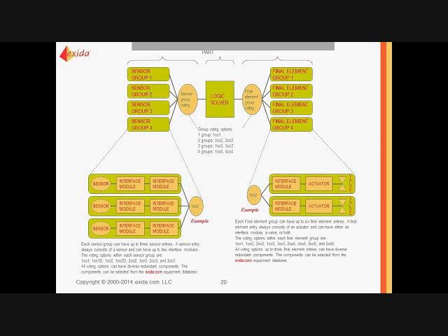A sensor entry consists of a sensor with 2 interface modules and voting options of 1 out of 1, 1 out of 1D, 1 out of 2, 1 out of 2D, 2 out of 2, 1 out of 3, 2 out of 3, 3 out of 3. So you have diverse options for voting and redundant components.